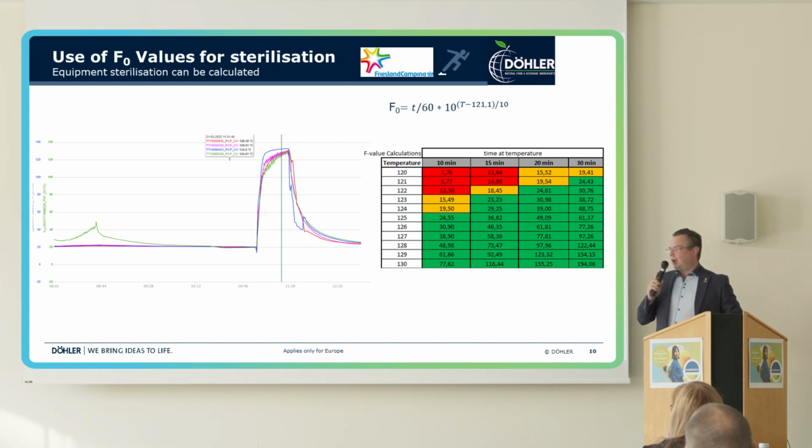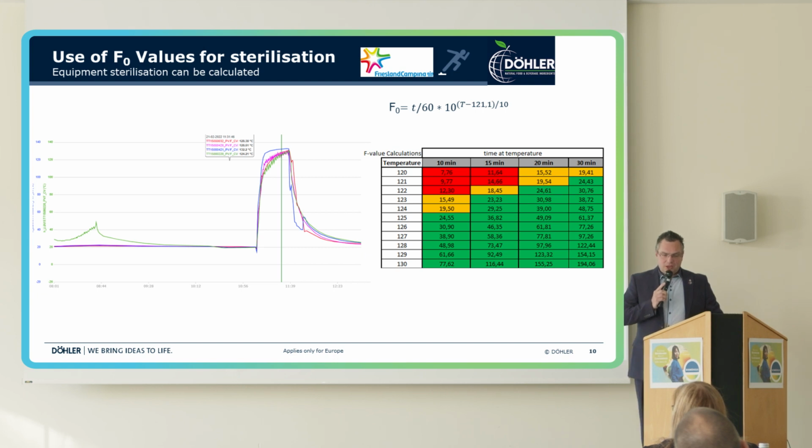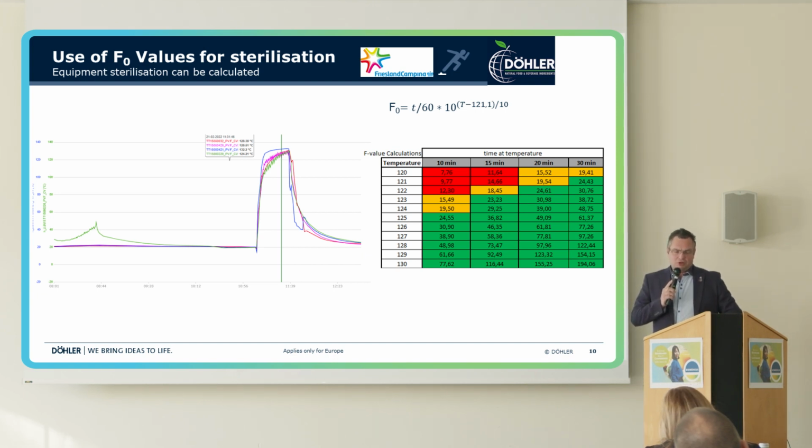Now, what you also have in terms of spoilage organisms in this type of field is Geobacillus stearothermophilus, which has a 12 log reduction of 42 minutes at 121. Which means that in these examples, the production setting should be around 138 to 141 degrees Celsius in order to obtain that log reduction.